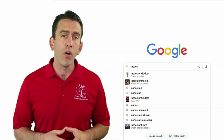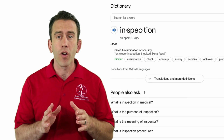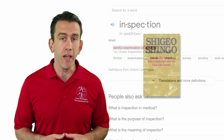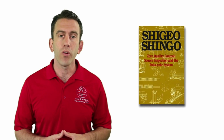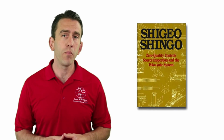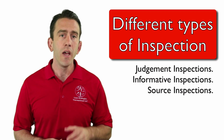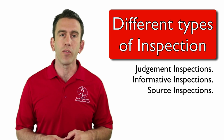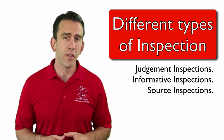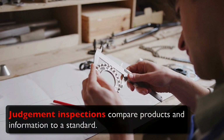A quick Google of the word inspection, and we find that it is defined in one way as careful examination or scrutiny. In chapters 4 and 5 of the book Zero Quality Control, Source Inspection and the Poka-yoke System, Shigeo Shingo describes 3 different types of inspection: judgment inspections, informative inspections, and the method used in the ZQC system, source inspections. Judgment inspections compare products and information to a standard.